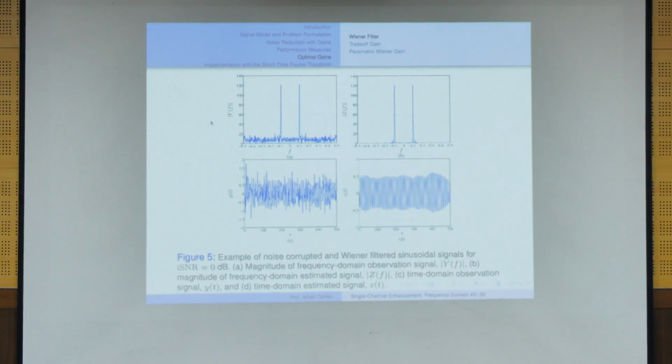But it's not easy to obtain the input SNR. When we work with the short time Fourier transform for speech enhancement, when we continue and reach speech enhancement, you will see, you can record your voice, add some noise, even white Gaussian noise, and then to know the signal to noise ratio for each frequency and each time bin in the STFT is problematic.